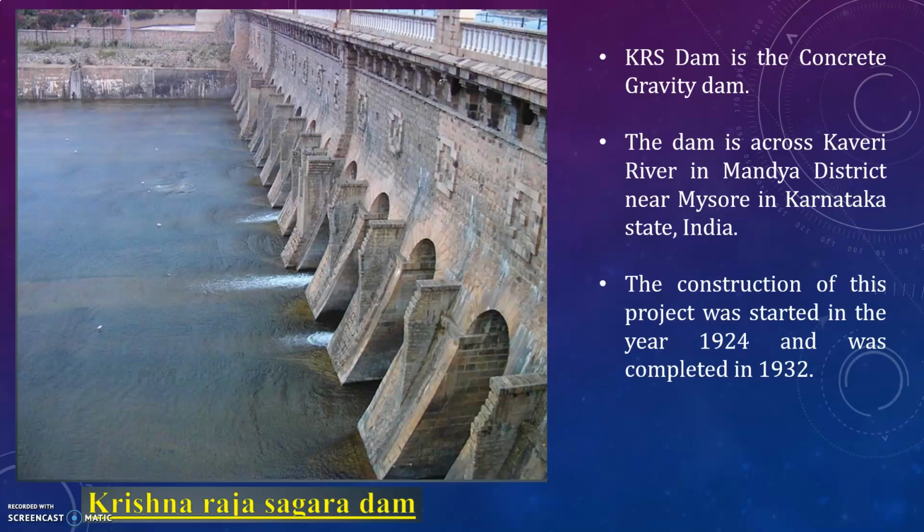Gravity dams can be constructed of any height provided suitable foundations are available to bear the stresses. The height of an earth dam is usually limited by the stability of its slopes, requiring a very wide base width. Highest dams in the world are gravity dams only. Gravity dam is specially suited to such areas where there is likelihood of very heavy downpour. The slopes of the earth dam might get washed away in such a situation.